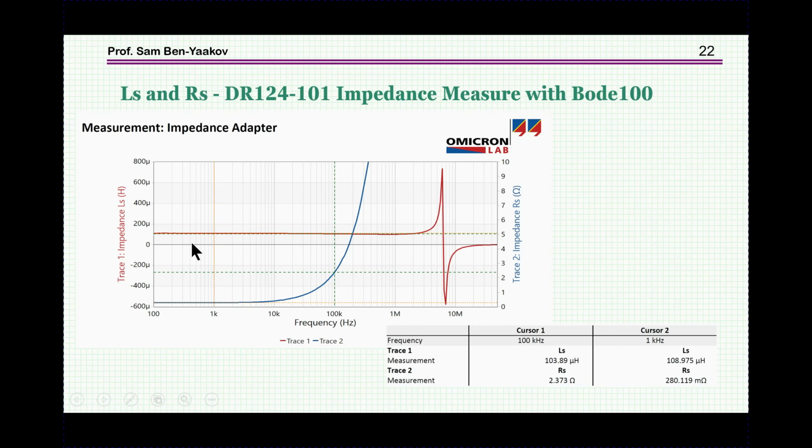So here we see the 2 components. We see the inductance. This is about 100 microhenry, this particular unit. Here is the resonance. So we see quite a bit of a change here, and of course this is not a useful region, and we are talking about, say, 1-2 megahertz. But lo and behold, see what happens to this part. This is the resistive part. And what we see here is that it started at fairly low values, and then it starts to shoot up at about 10 kilohertz, and above 100 kilohertz, it goes very high.